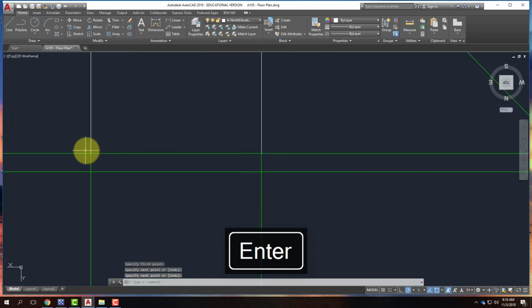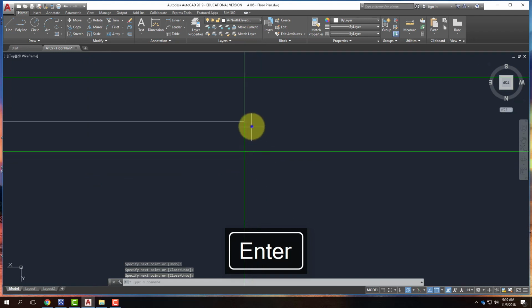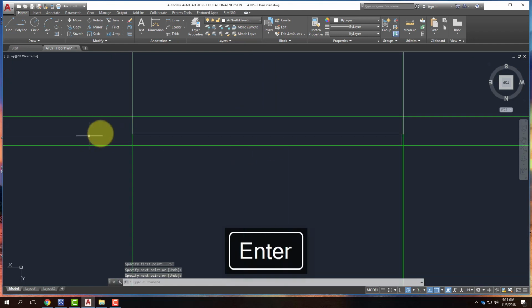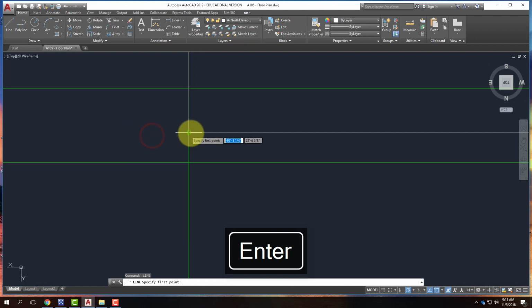Same thing applies where I'd go another foot down, 1 foot. I'd come over and go back up. And then 2 more little lines that are over maybe 3/4 of an inch and come down to right there. That's a technical detail that just makes your drawing look more realistic. It gives the impression that you actually know that a building is constructed of materials.